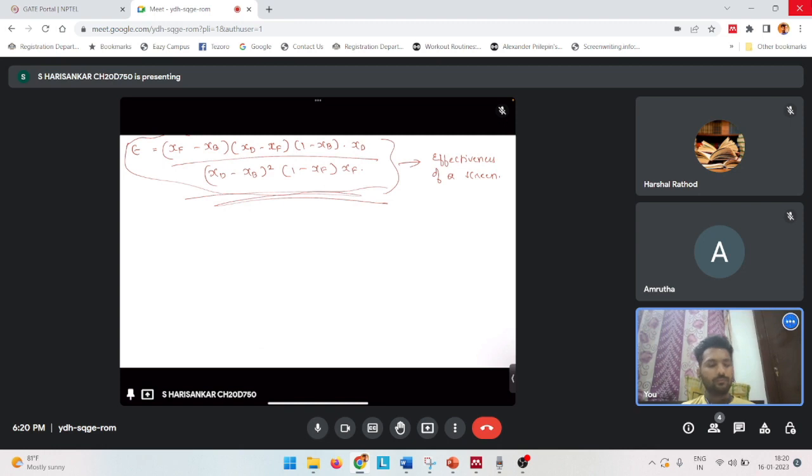Right. Now when I say these mass fractions xf, xb, xd, as I said, these are usually defined based on overflow products. You can also define them based on your underflow product. If you are defining this in terms of your underflow product, you will have to write these mass fractions as xf dash, xb dash and xd dash. And xf dash will basically be 1 minus xf.